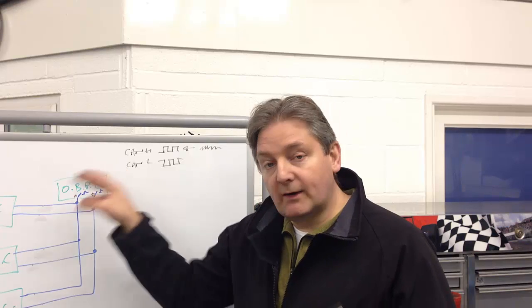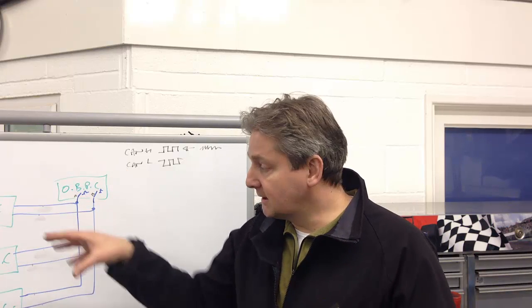We disconnected our faulty unit. The waveform came back square. We just made sure that we didn't have a wiring issue causing that fault, and it looked like we didn't. We committed to ordering a new unit. The new unit's £250 plus taxes, and we plugged that unit on this morning. We verified the fix with the waveform. We verified the fix with the function of the car, and essentially we've sorted out this car, which previously had arrived here with another component fitted in a misdiagnosis situation.